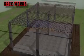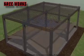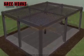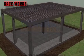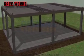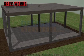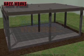Slab shuttering. Beam bottom is first laid on the column, and then slab shuttering is laid. Beam and slab levels should be maintained as per drawing. Slab concreting. After the concreting of column, beam and slab concreting shall start monolithically. The top of floor beam and slab shall be maintained as per levels.